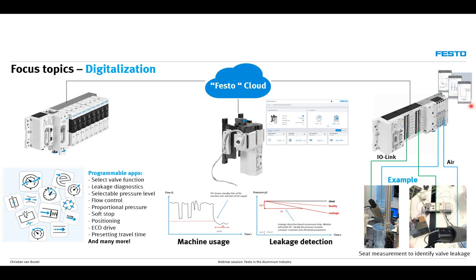So a part of predictive maintenance can be integrated in all standard components, but because of the platform and the available dashboards that can communicate through the cloud, we can make this information easily available to your team. Also, you can think about the usage of pneumatic valves. Do you know, for example, how often a pneumatic solenoid valve is switched or operated? These dashboards will give you a direct figure about the performance of it, but also the expectations of when the product might be failing.